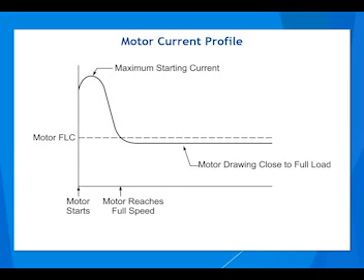But it is that initial bump as soon as I energize the circuit that causes problems within the circuit if I have my fuse ratings too low or if I do not use a time delay fuse. That bump might only exist for a fraction of a second, but that fraction of a second is enough to blow most standard non-time delay fuses.